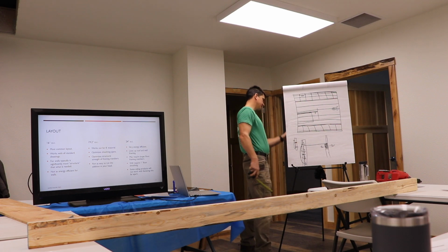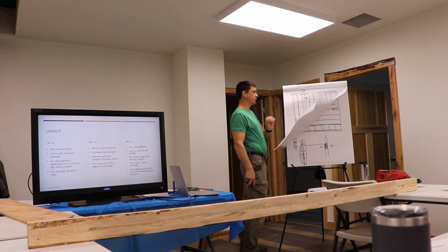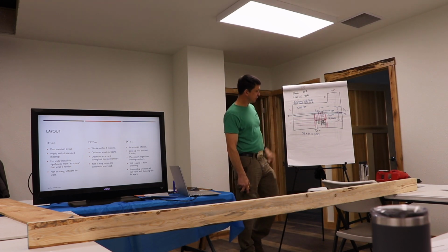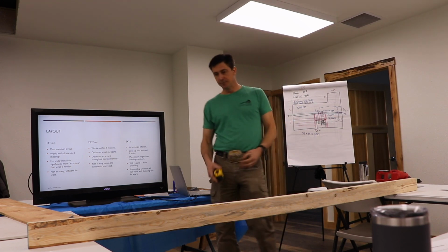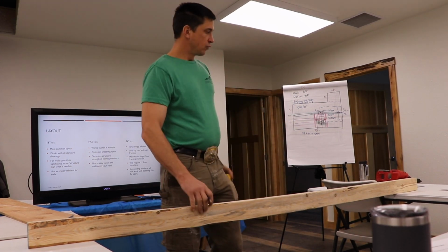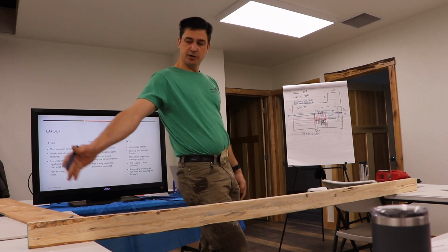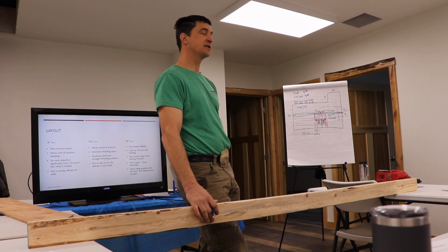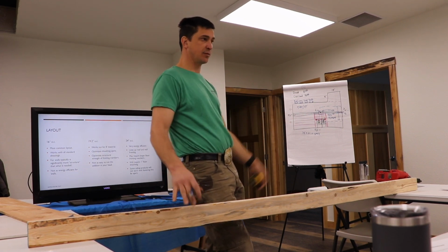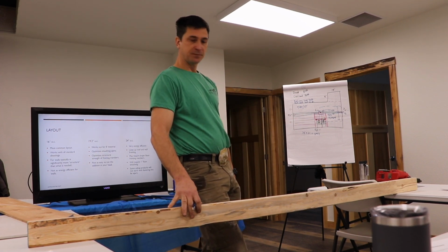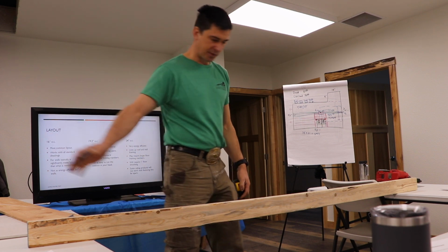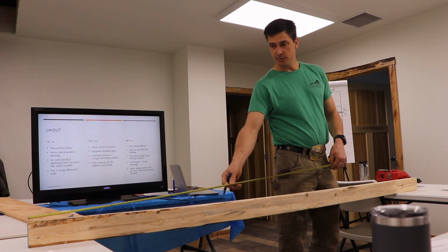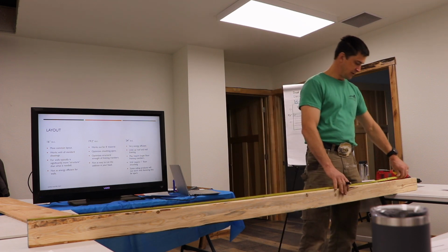Let's go back to this floor plan, wherever it was. There we go. Okay. We got a 52-foot long wall. So we're going to frame this thing. We're going to use 16-foot top and bottom plate lumber. So I run my layout, and let's say I'm using a 2-foot on center layout.